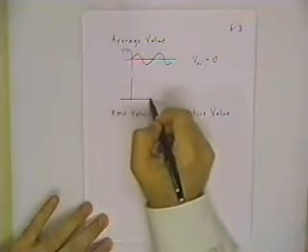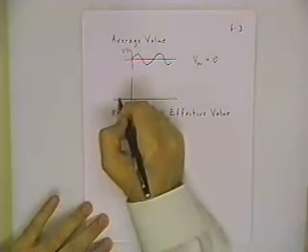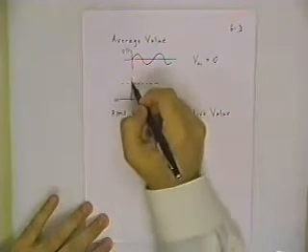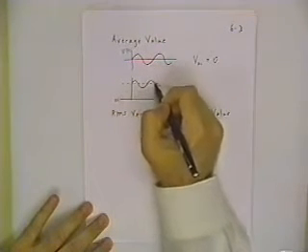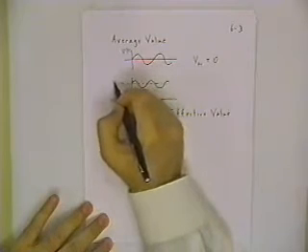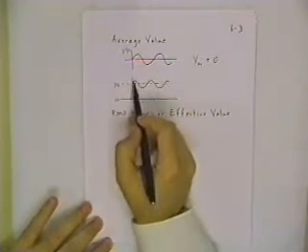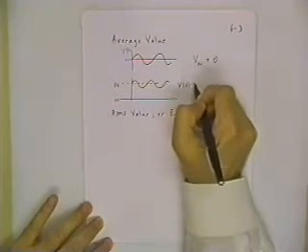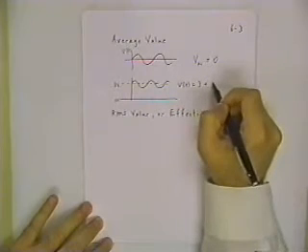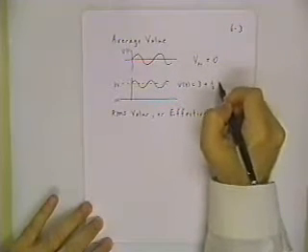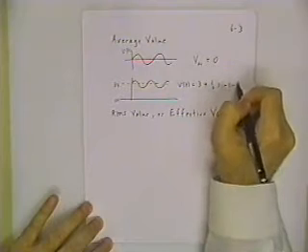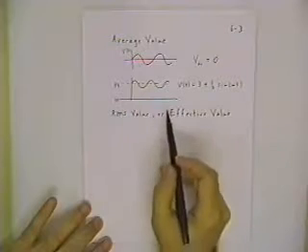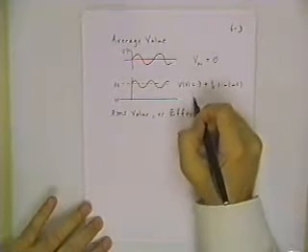If, however, you've got a case where here's the 0 volt level, and what you've got is an AC signal riding on top of a DC signal, and let's say this is maybe a 3-volt line, and we've got perhaps a half-volt amplitude waveform. So V of t here would look something like this: 3 plus 1/2, and I'll just go ahead and call it sine of omega t since I started off at the 0 value at t equals 0.